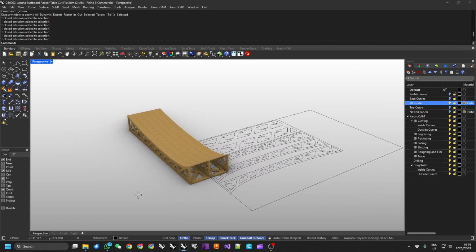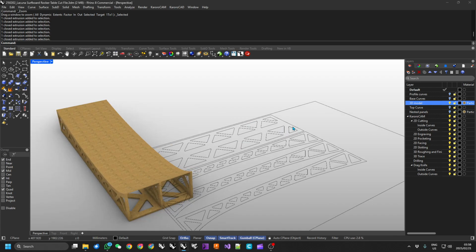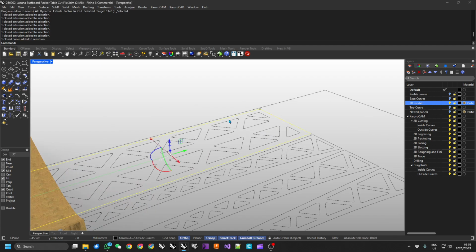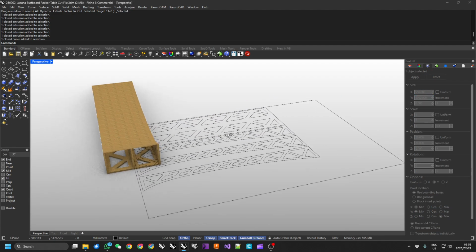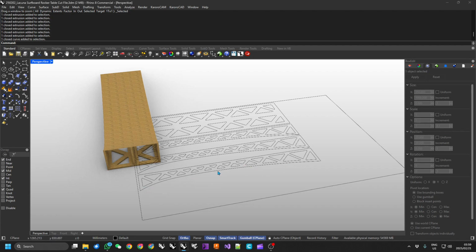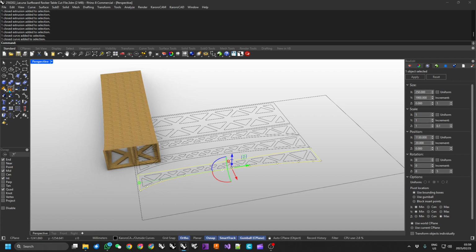surface. Now, the easiest way to find the dimensions of this is to look at this base, which is 550mm by 1900mm, and then to get the length over the curvature here, I'm just going to explode this cutting curve and type length in Rhino, and we've got 1928.5, or effectively 1929, is the overall length across that curvature. So I'm going to copy